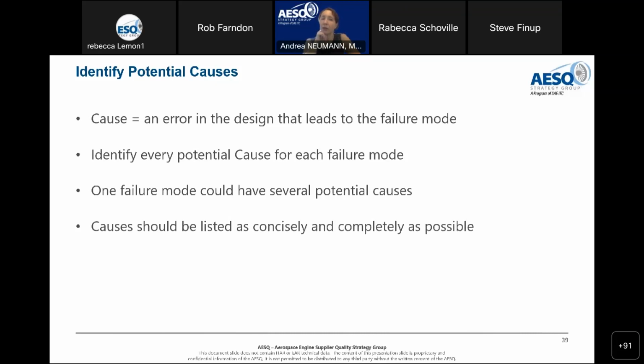But later on, I just go further down with the components and the items and just define there how the item could fail and how features could be wrongly designed. So at the beginning you maybe have a higher level because you have not enough information, but further in the process you go further down until you have the lower level systems and the causes there.